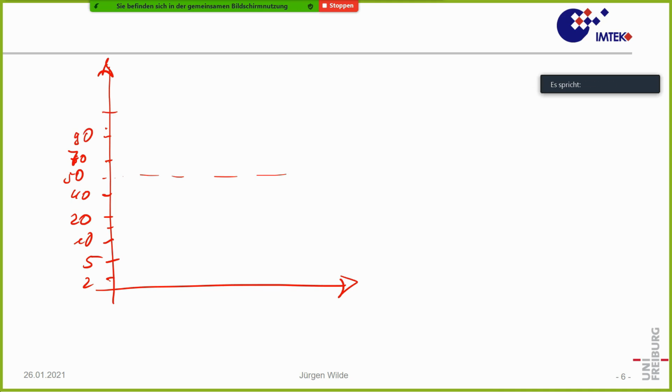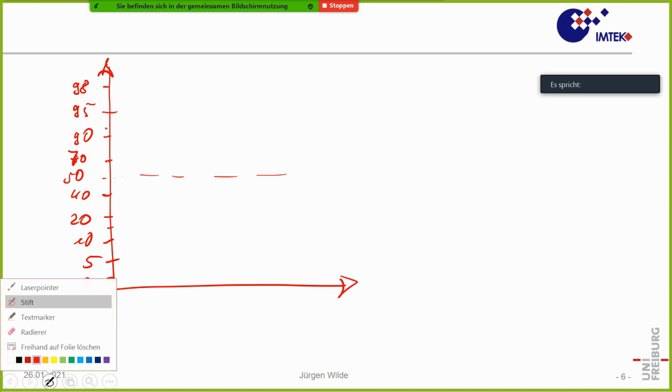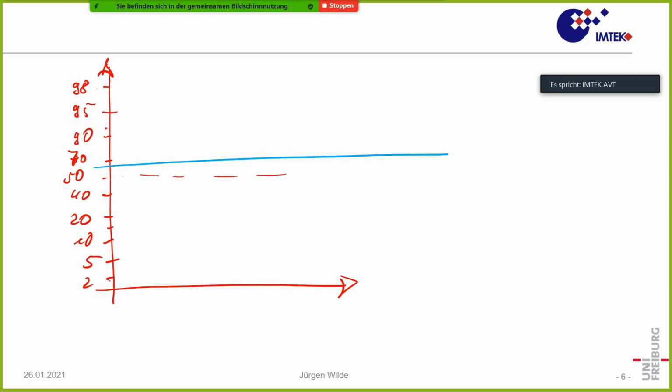For instance, when we look at Weibull plot, we would have to plot in a way that the first percentages of failure will have a large distance on our plot, while between 40 and 70% of failure, it is plotted in a compressed way, and again at the end we have large differences on the scale between small percentage differences.